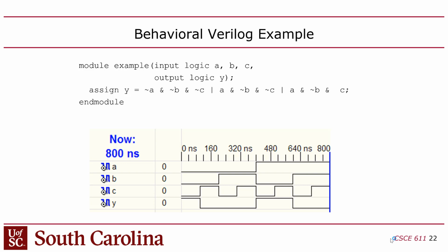Now you can go back, by the way, and you can synthesize it and put the delays back in. You can model the delays. I never do that because there's a better way to do that, called timing closure. When you tell the synthesizer, look, I want the critical path delay in this circuit to meet my timing requirement of 400 megahertz, which means the critical path has to be less than 1/400 millionth of a second. As long as you can meet those requirements, that's generally how it works.